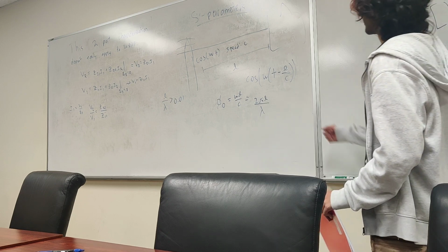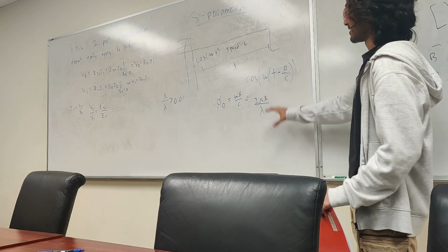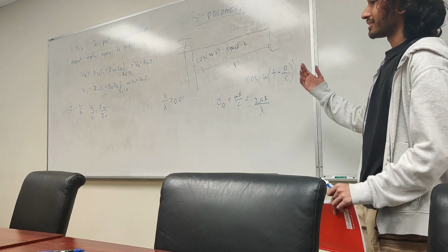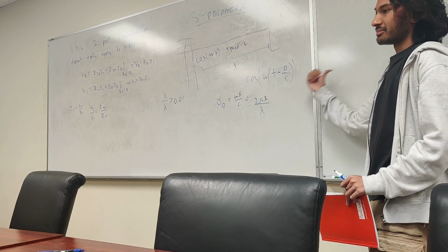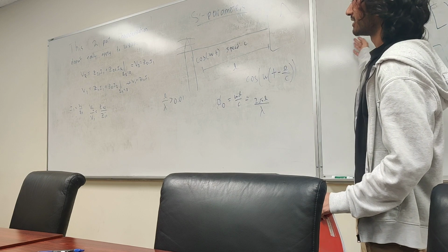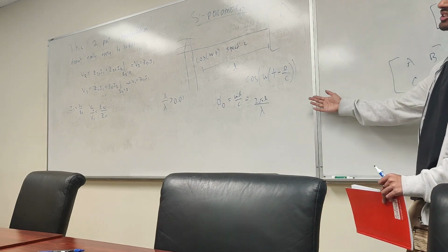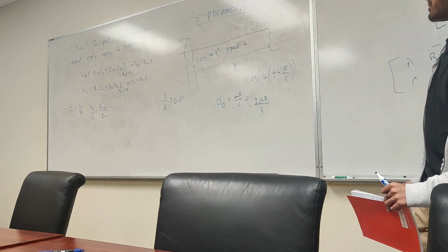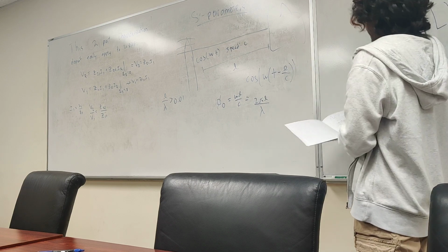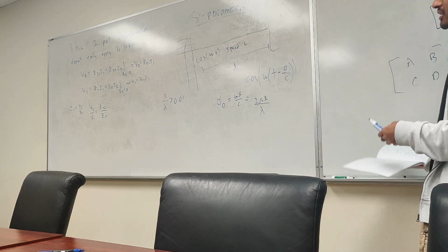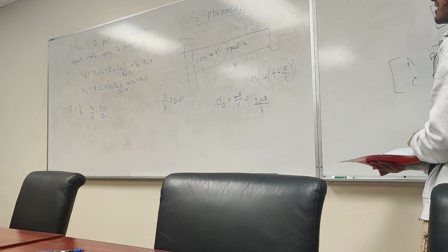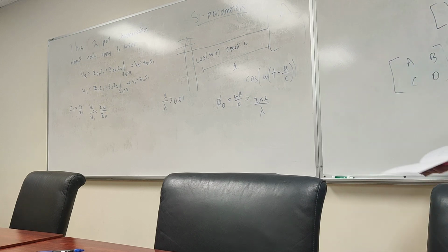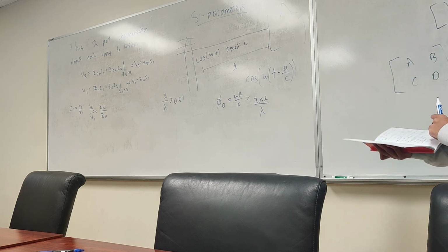Because in microwave theory, when we talk about S parameters, and I'll get to this soon, we care about transmission lines. And when we have transmission lines, that's assuming that things have reflection and transmission. If you have a normal voltage divider, you're not going to have reflection of a signal. But if you have something super long and things are not matched, 50 ohms for example, you'll have reflection. So that's what we're going to build up to, and S parameters are based on this notion of reflection. Despite us not really having reflections at 27 megahertz, we can still utilize S parameters, and I'll walk you through why that's still valid.